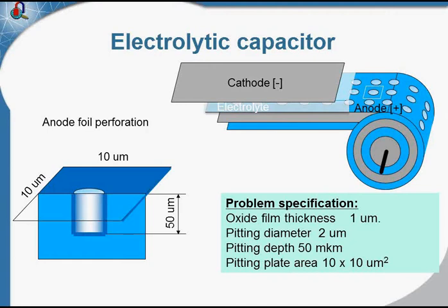I will simulate the electrostatic problem because I would like to calculate the capacitance, and there is no electrostatic field in the conductors. The electrostatic field is concentrated in the oxide film. So I will simulate the dielectric media only, the oxide film.